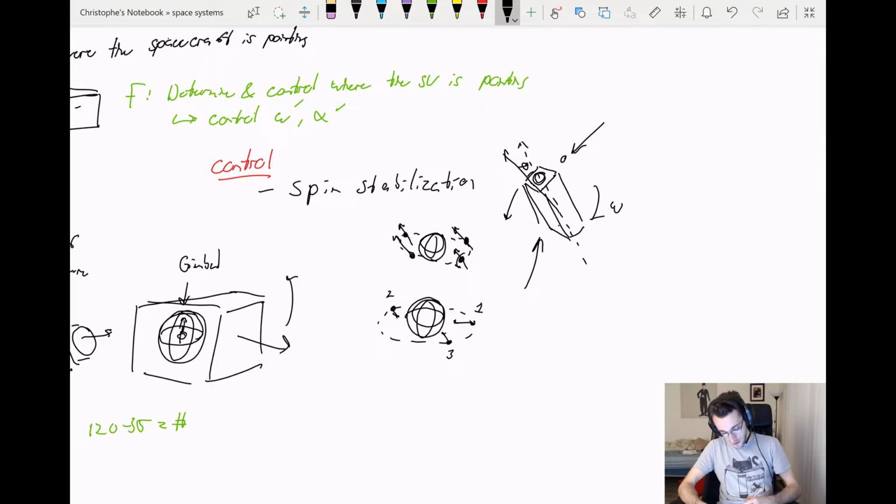Which means that as you're orbiting, you want to be rotating about an axis perpendicular to the plane of your orbit at the same angular rate that you are making your orbit. For circular orbits, it turns out that the rotation around your own axis is going to be constant, which is nice. You can just set a certain constant rotation of your satellite, so as it goes around its orbit, it's constantly looking at the Earth.